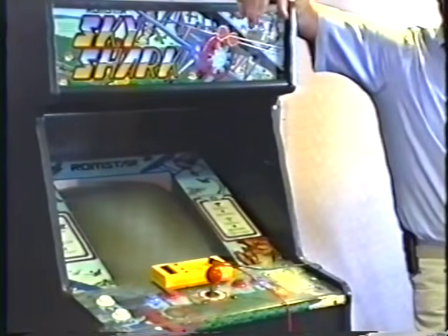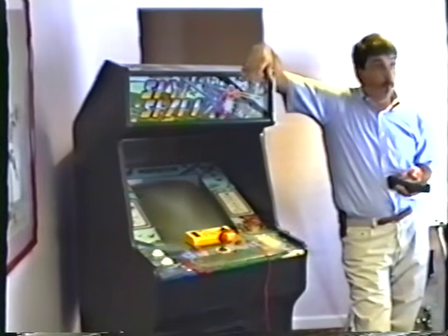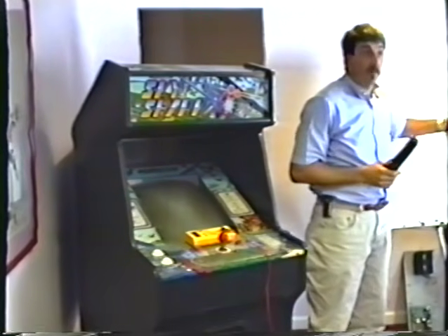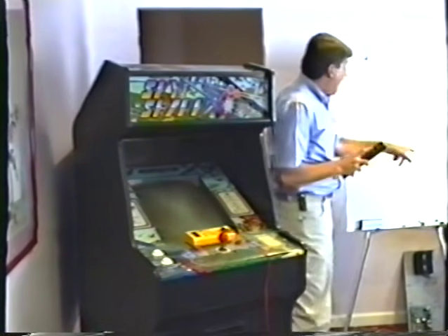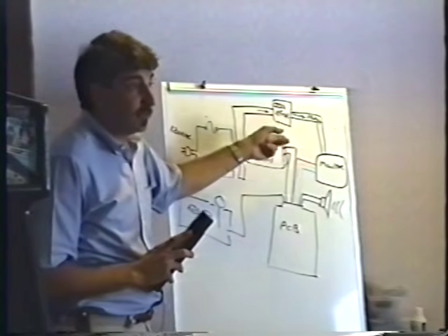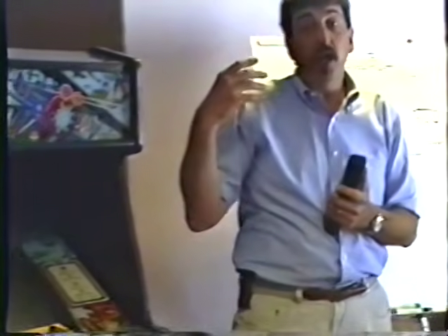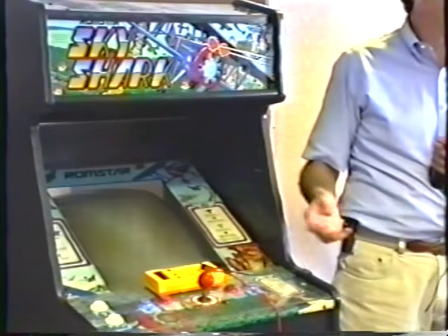See if you hear all the game sounds. If you hear all the game sounds, that must mean that the computer's working, huh? If the computer's working, the power supply's got to be working too, huh? If the computer's doing its thing, the power supply's good. So right away, as soon as you coin it up and you hear all the game sounds, you know that the power supply is good, it's plugged in, the computer board is good.